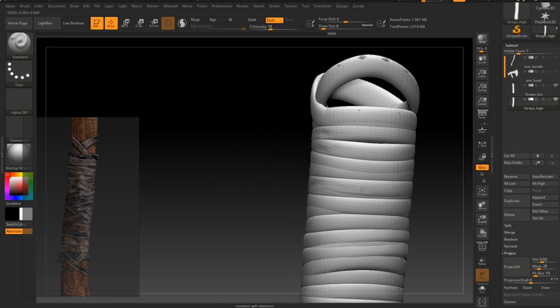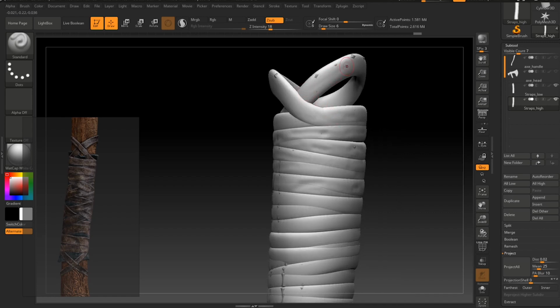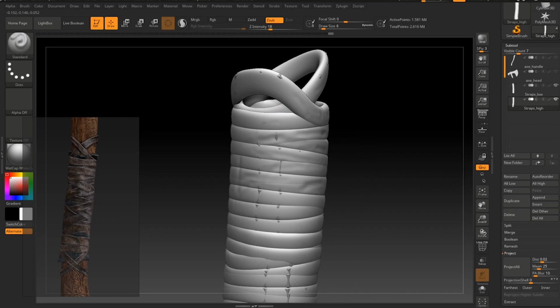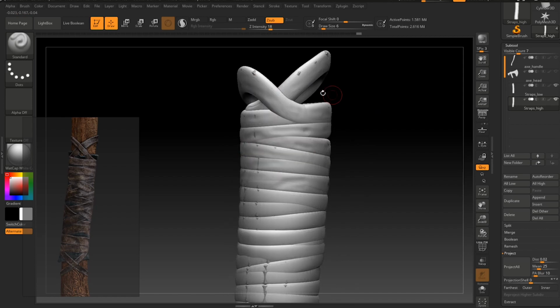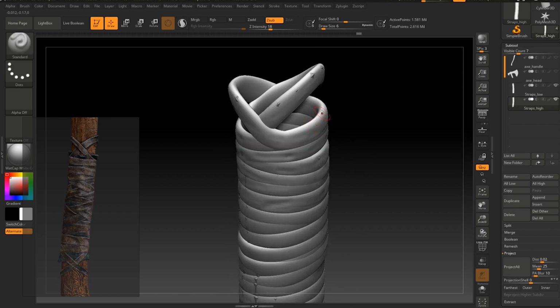That's where the low poly comes out of the high poly a little bit. Again, we won't have any problems with the normal map, but if you put too much pressure in there, you will create that problem. As you can see, our smoothing effect from having these extra subdivisions has in a way created too much of a smooth corner. I'm not really that fussed about it, to be honest.